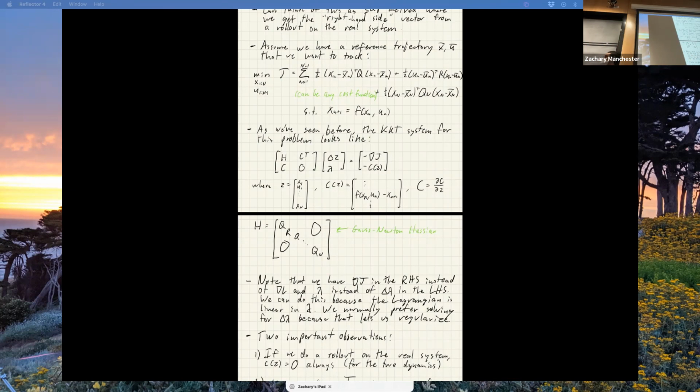So the idea here is I have some system. I have some model of the system that's f of x, u, but the model's not 100% correct. So what do we use to actually do the rollouts? The real system. Yeah, so I have the math for this thing that I'm going to use in the computer to compute this stuff. Then I'm going to take the controls that I get from that, go run them on the real thing in the real world, and log data.